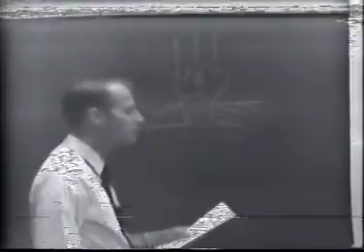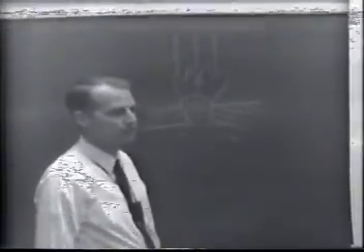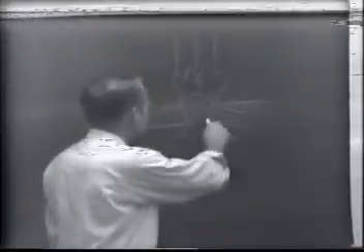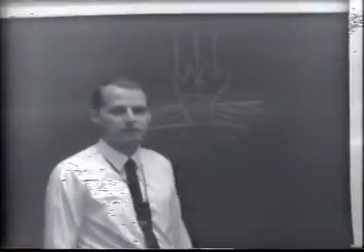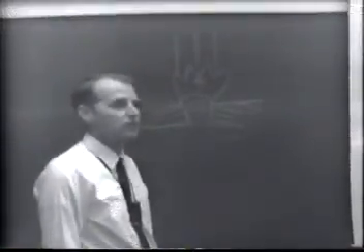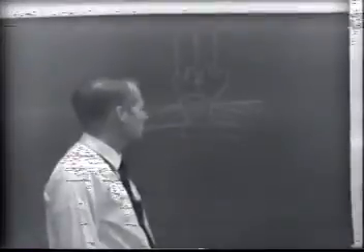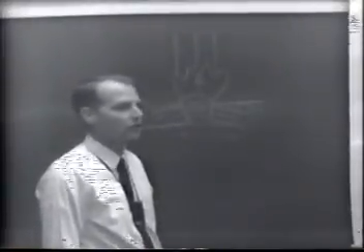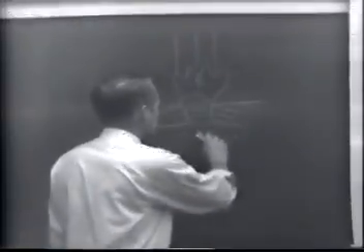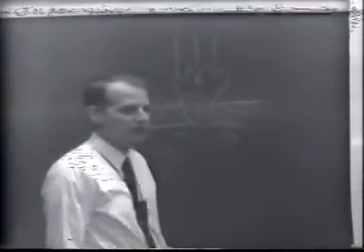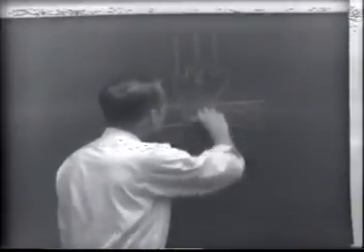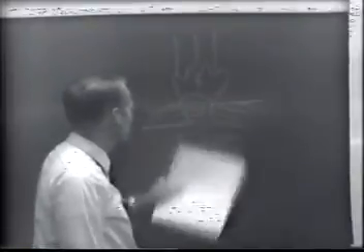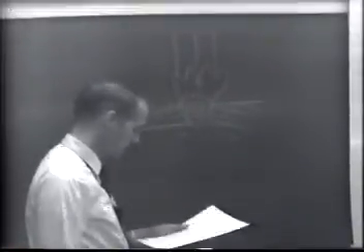In increasing the dielectric strength here, one way of doing that, of course, is introducing new material, fresh, cool material into this arc space here. And we can do this in several ways. In several types of breaker, we do it by a blast, forcing air or oil or some other gas into this space here. This would tend to cool the contacts, cool the arc, and establish the original dielectric strength between those two contacts.